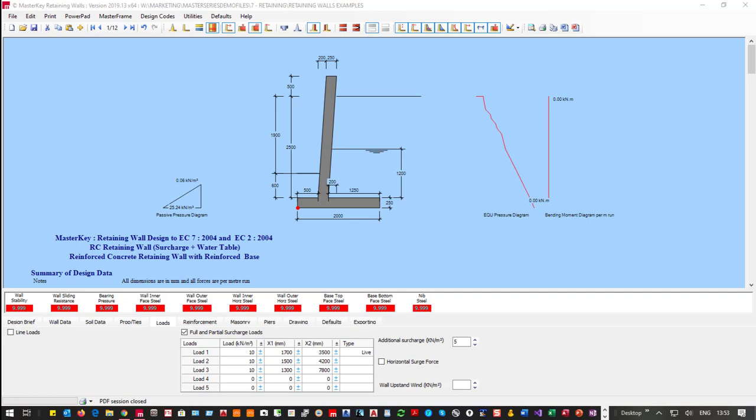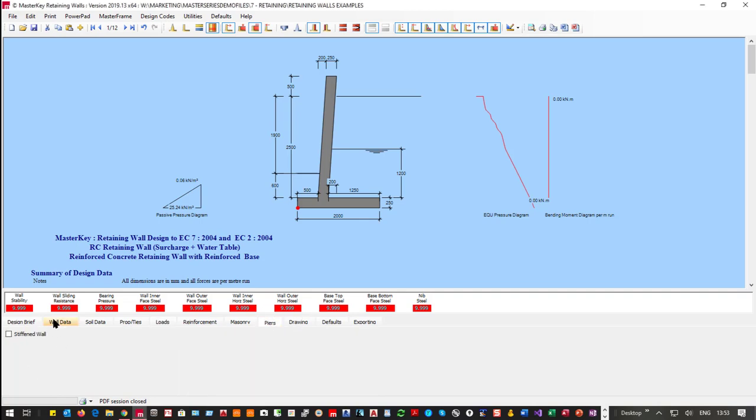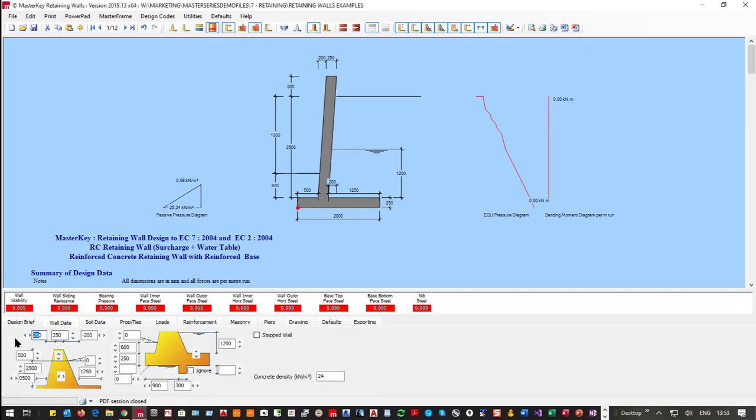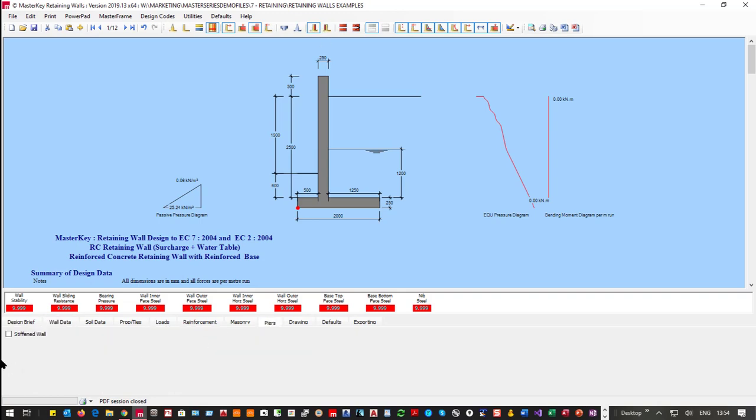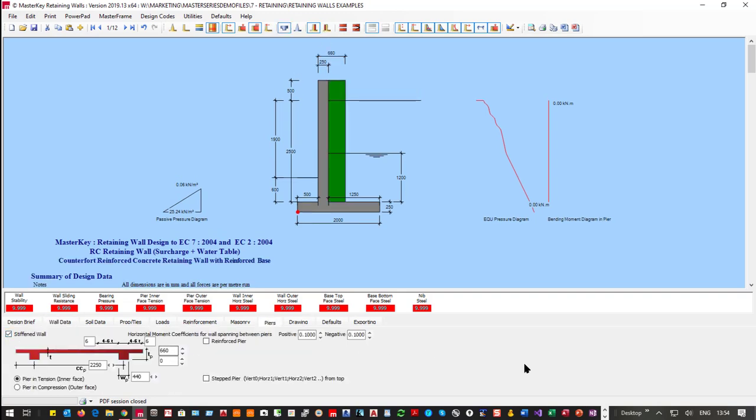Counterforts and buttresses, piers, that's what they're called. So let's get back to the wall. Let's get rid of this silly sloping and over sloping. Let's now come and say we want to come to piers. Yes, you can go for stiffened piers and have counterforting and then spanning in both directions. So absolutely, yes, you can do counterforts.